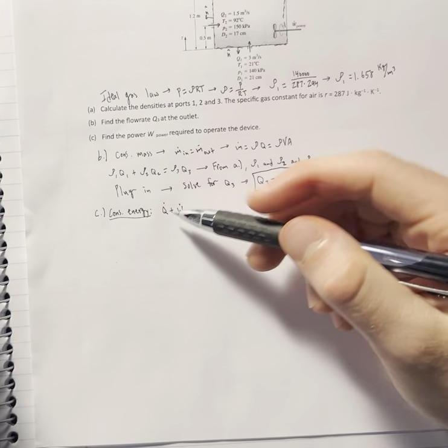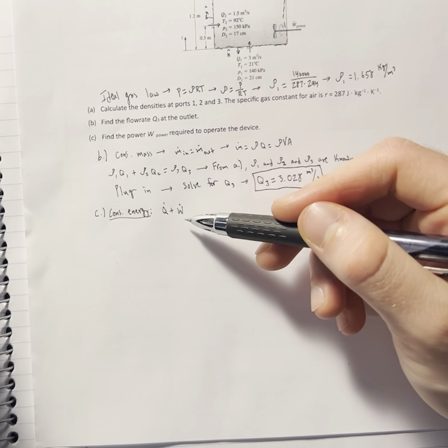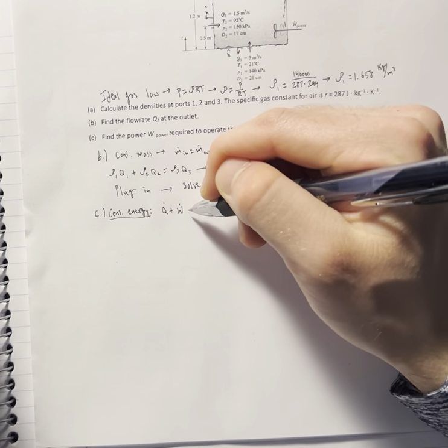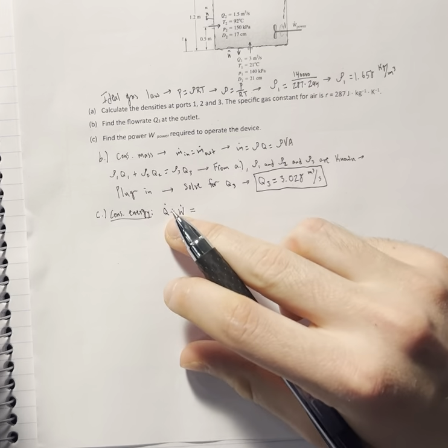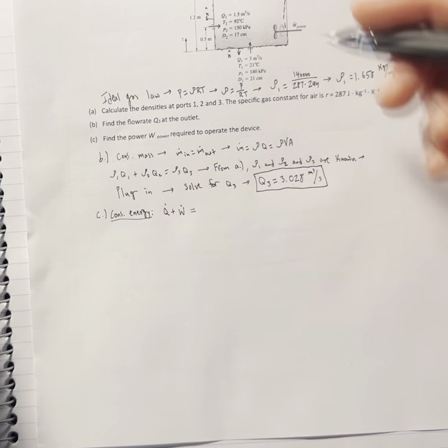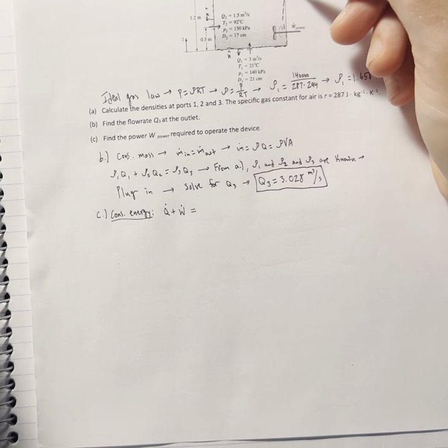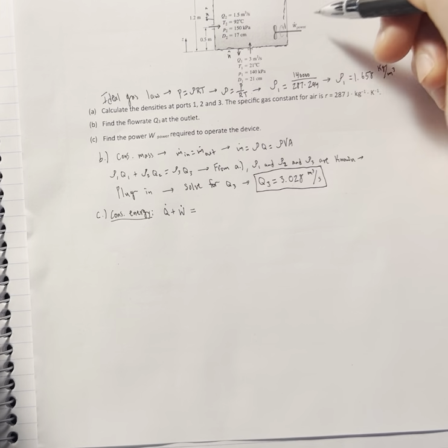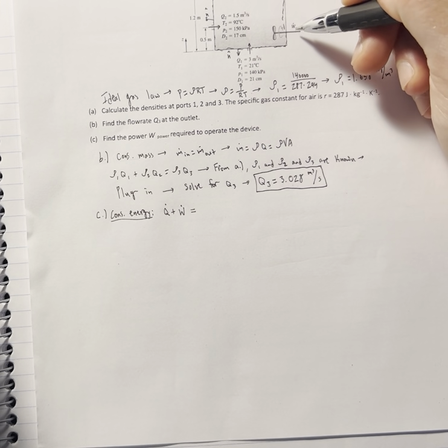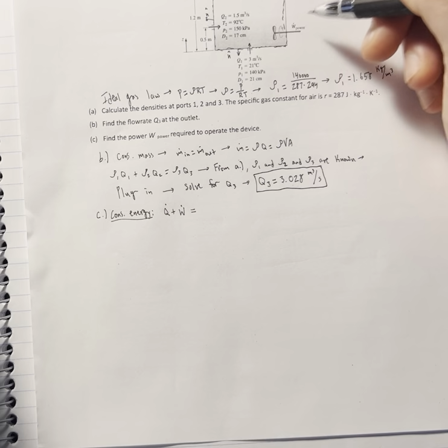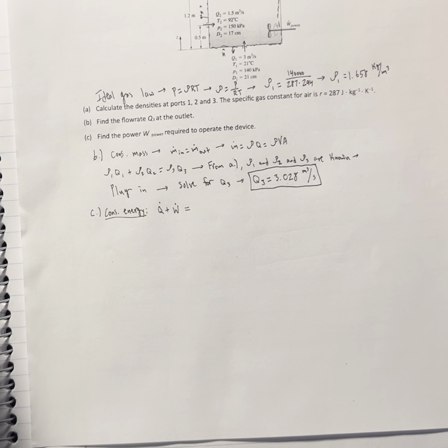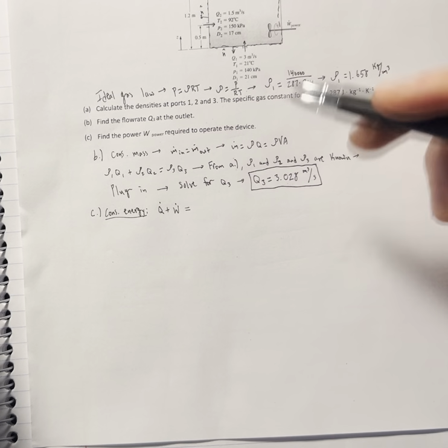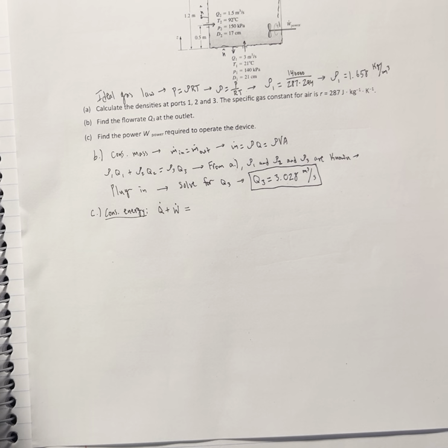So basically, the net heat flux plus the net work being done. And it just happens in this case that the only heat coming in is 67 kilojoules per second. And then the only power being provided is by this WP, we'll call it WP up here. This can be shaft work, this can be viscous work. If you took thermo, you know all the different ways of providing work.